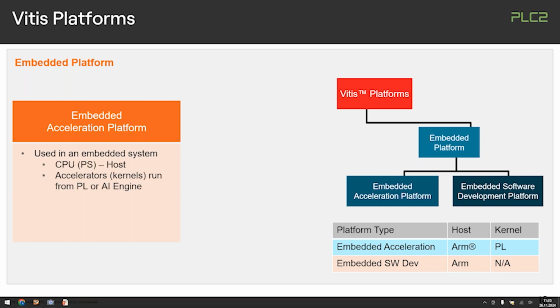So basically, you have the base platform, you have the CPUs that can run any kind of application, and you are talking about extensions that would be kernels in this case. And these kernels are basically controlled by the CPU. So typically, where you come from, you would be calling a C function on the CPU, but you think to carry it out physically in the hardware. That's one way to think about this kind of acceleration approach.